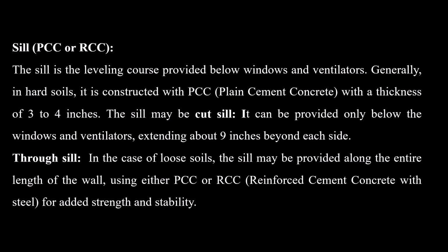Sill, PCC or RCC. The sill is the leveling course provided below foundations and ventilators. Generally, in hard soils, it is constructed with PCC, that is plain cement concrete, with a thickness of about 3 to 4 inch. The sill may be cut sill. It can be provided only below the windows and ventilator, extending about 9 inches beyond each side for the bearing, and through sill. In case of loose soil, the sill may be provided along the entire length of the wall using either PCC or RCC for added strength and stability and also to avoid cracks.